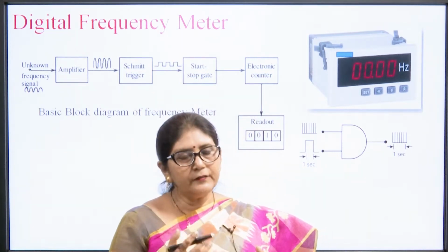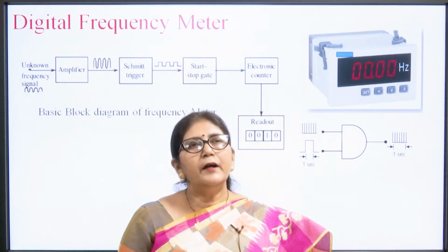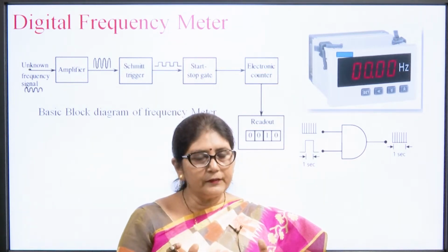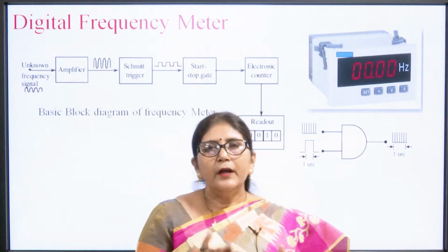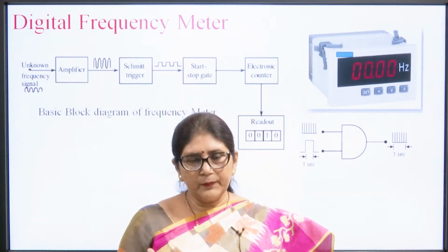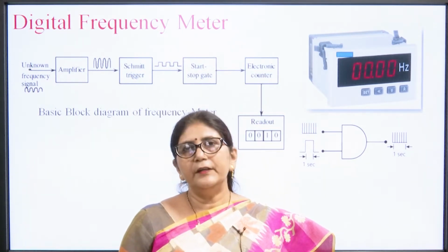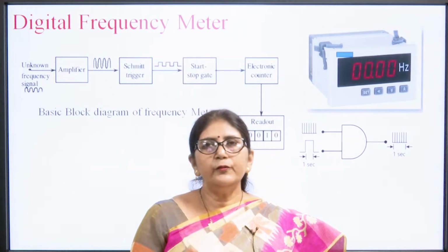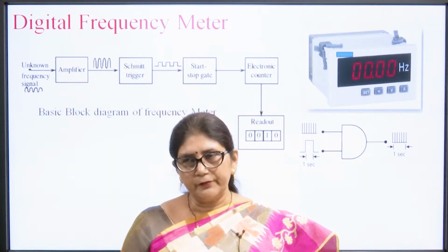Suppose we have designed an oscillator by calculating different component values, and after designing that oscillator, we want to measure whether the designed oscillator is producing the same frequency that we expected or it is producing a different frequency. So, that oscillator we can measure by this instrument, that is the digital frequency meter.